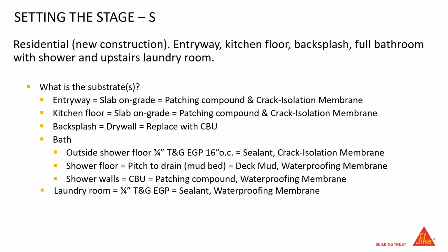Crack isolation membrane. You know, we are a manufacturer of crack isolation membranes, just like there are a lot of other manufacturers of crack isolation membranes. And we look at crack isolation membranes as insurance. You either have existing cracks or soon-to-be cracks, because what types of substrates are there in the industry? There are two: cracked and gonna crack. So that crack isolation membrane, we recommend it on every single tile application that's going over a concrete substrate. Crack isolation membranes will help alleviate that existing or new crack from telegraphing through that installation.